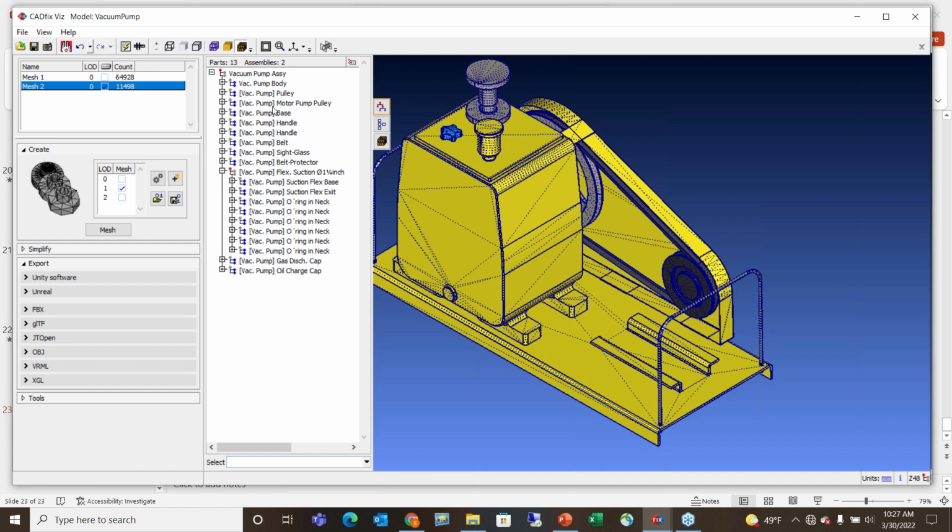All right, it looks like we have a few more questions, so we'll go ahead and take those. With CADfix Viz, a mesh is stretched over the existing model, and we've reduced the triangles as needed. Is that correct? Yeah, ultimately there's a mesh, and the decimation definitely reduces the triangles. That's a targeted approach in the background that is essentially trying to remesh areas and faces of the model with fewer triangles.